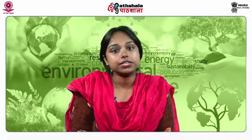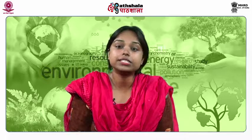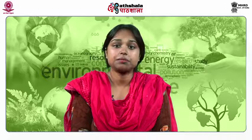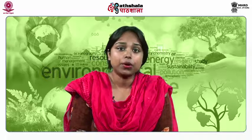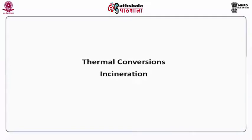Currently, biological and thermal processes are frequently used to convert municipal solid waste into energy. Now, depending on the type, quantity and physico-chemical characteristics of waste, different techniques like direct combustion, gasification, biomethanation, refuse-derived fuel (RDF) are adopted to produce energy from waste. In India, various projects are underway to convert waste to energy. Now, first is thermal conversion.